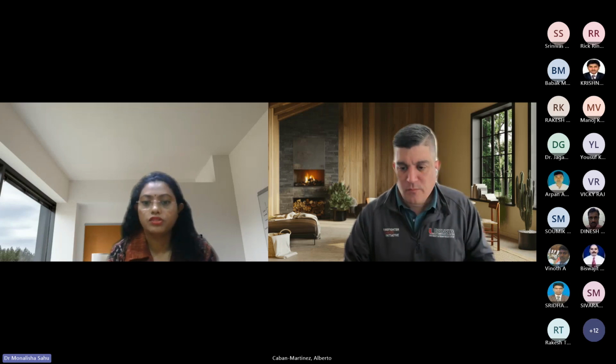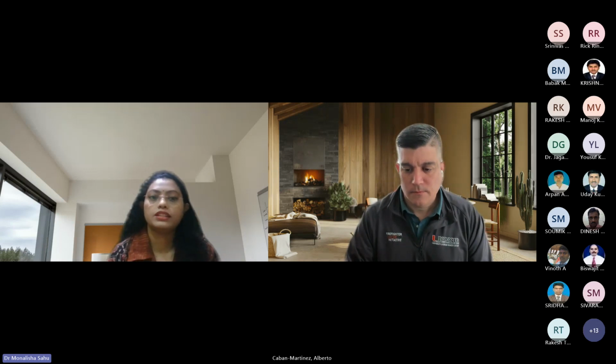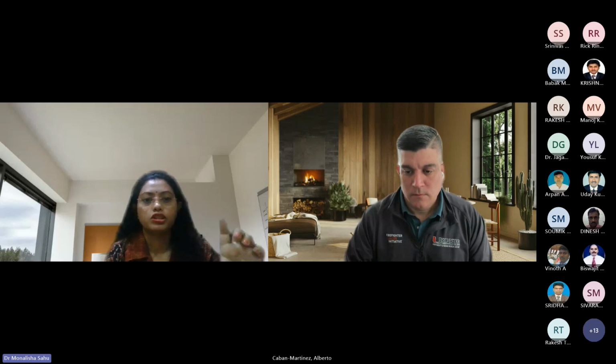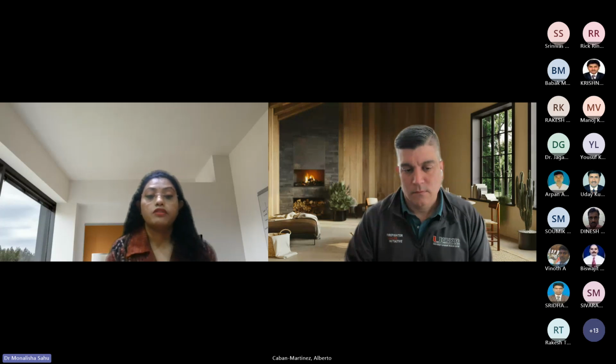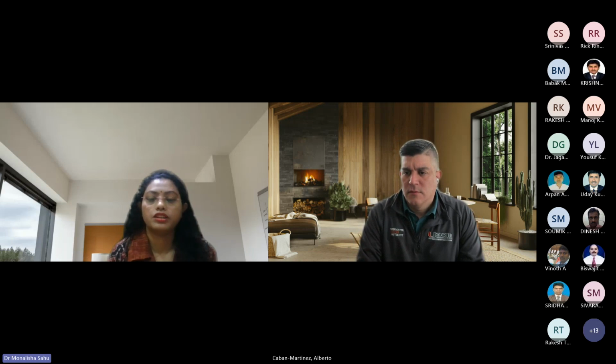So first of all, if we can generate awareness before taking any measures, it is very important to train the workers also. A small duration of training, at least, when we can talk about various hazards, what they are, specifically about the clothing, and specifically about maintaining hydration. Because you will see many times when workers work at height, in the morning they will take a bottle of water, they will go up, and then they won't come down, and the bottle of water is over. But so that their work is not hampered, they're not coming down. So first of all, it is important to make them aware of how dangerous this habit can be. And when they are aware of that, they can maintain their clothing and their hydration.